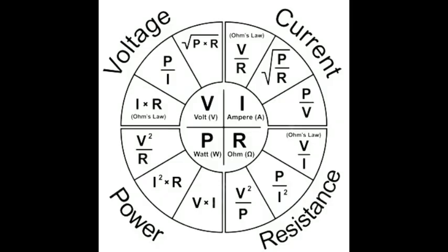So do we have enough values there to solve for everything using Ohm's law? Yeah, right? Do we have to dive into the formulas there? No. No, but it is because you are paying attention to what are the rules, what applies to each one of the circuits. So now here, you just need to take 6 times 3 gives me how much? 18. So it's total 18 watts. And 6 divided by 3 gives me 2. 2 ohms of resistance. Now that's the total resistance of the circuit.